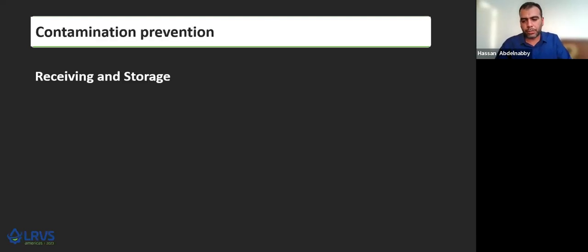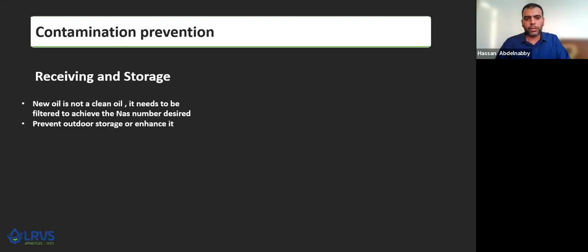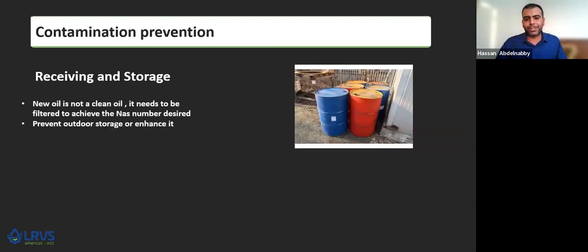So the prevention from receiving and storage, of course, your oil is not clean. If you get a new oil, it's not a clean oil. You need to filter it in order to reach the certain cleanness that you need. And of course, outdoor storage is not a solution.